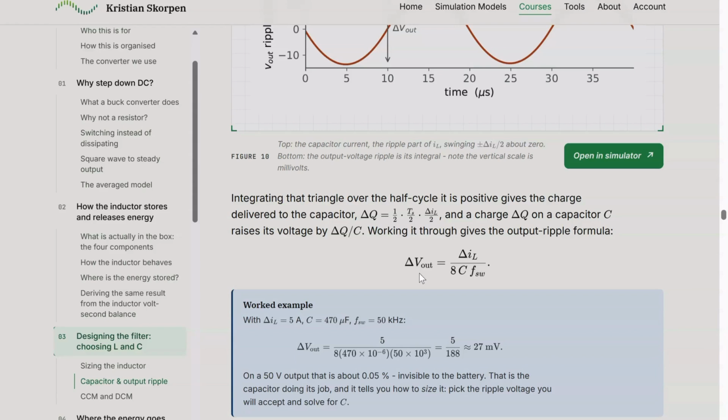So in order to design the capacitor, we actually design the ripple that we want using this equation. So we could either solve for the capacitance if we want, or just adjust the capacitance until we get the ripple that we want. And now the switching frequency is often determined for something else and not for this voltage ripple, but that would depend on the system that you're designing, like what the buck converter is used for. So that is basically how you can do this.